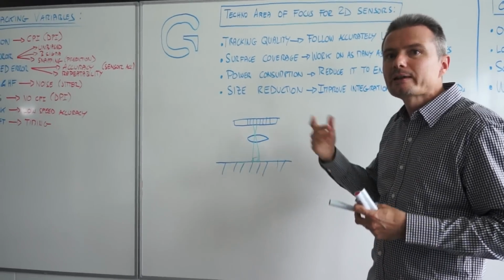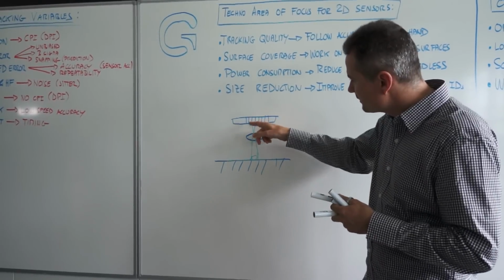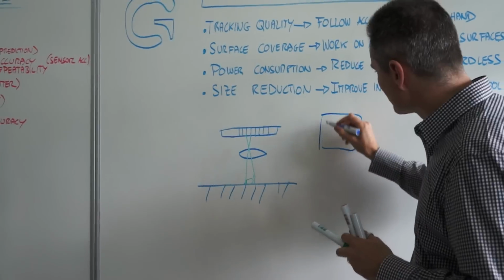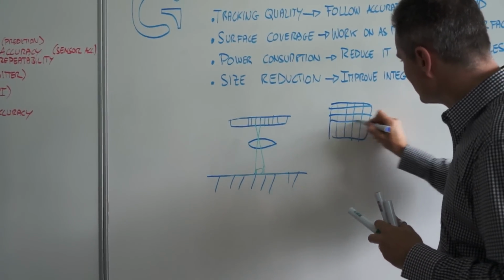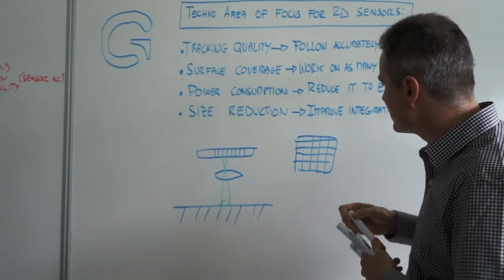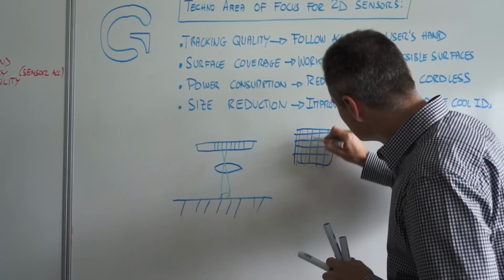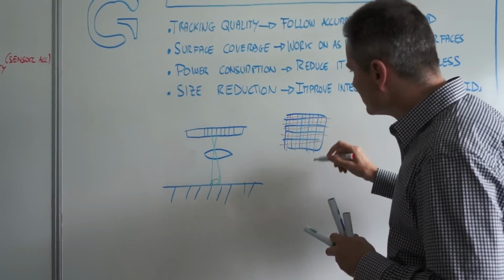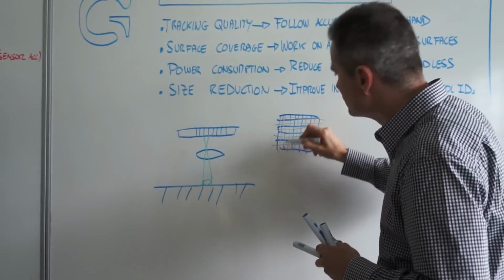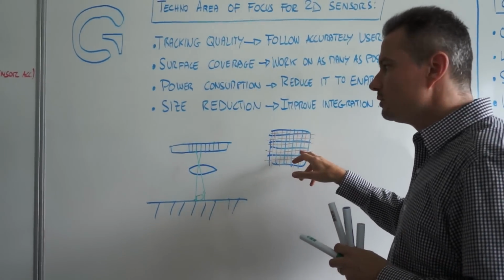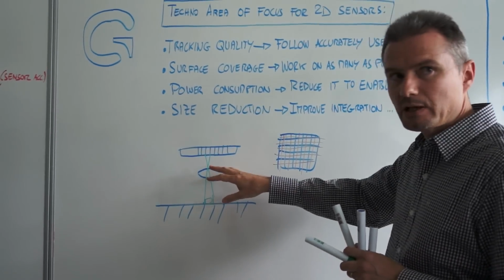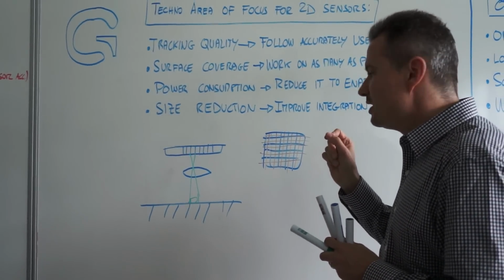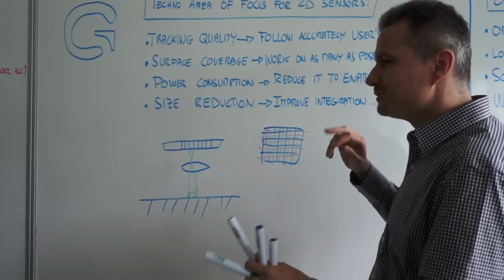So how can we build higher DPI? We can build higher DPI by subdividing the pixels. So if we look at it again from the front, we see this is the matrix of pixels. What we can do is subdivide. Each pixel, we cut it in 2. So in that sense, we double the resolution. And then again, you can double it again by cutting it by 2, and so on. By doing that, you are going away from the native resolution, the optical resolution, but you are improving the sensitivity of the system. The drawback is that